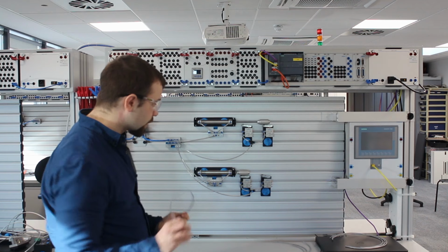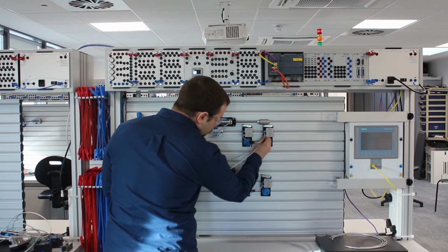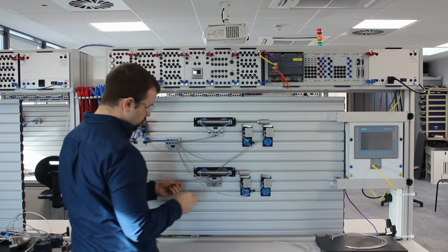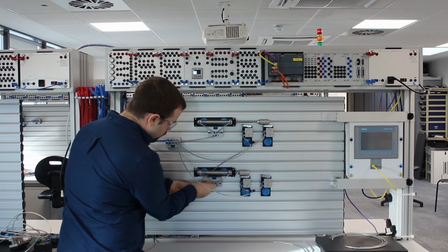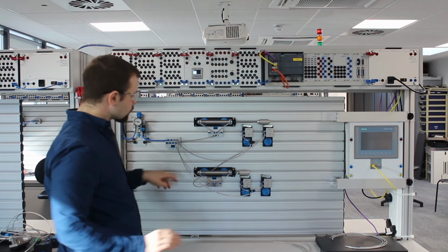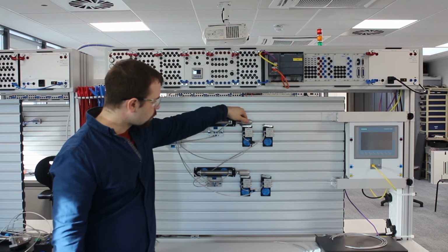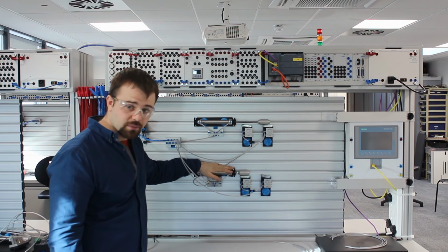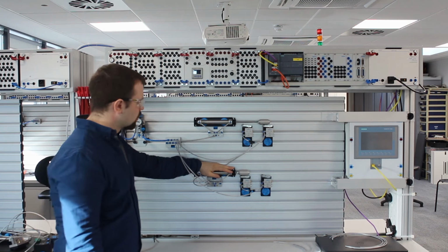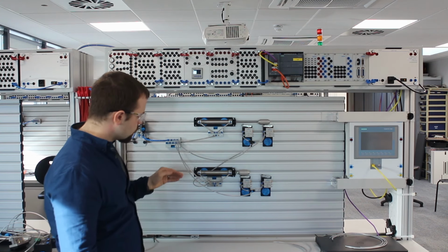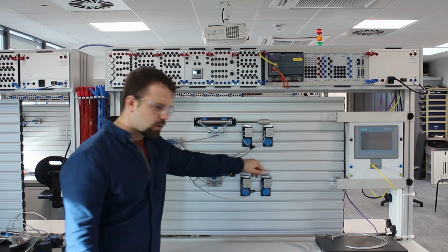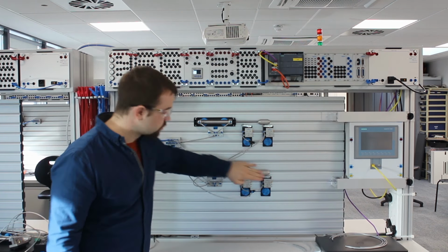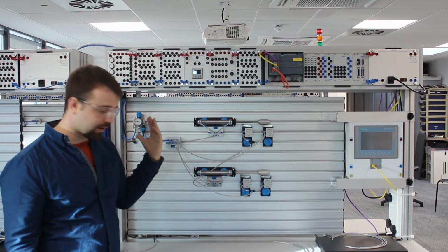No way of really getting around this, we're going to need a long pipe. So from 2 on the roller switch, I'm going to pass it behind the cylinder, just for ease, and into 1/4. So now, this will roll forward, hit this switch, that will cause this to extend. What's the next action? Well, we have A+, B+, A-. So what we need to do is use this switch to trigger this to come back.